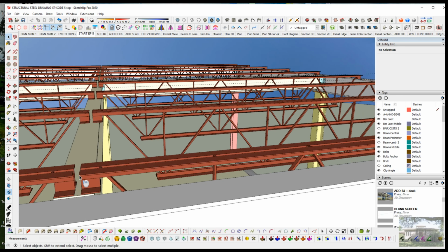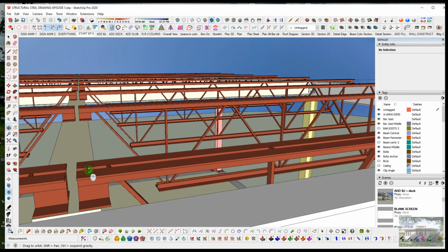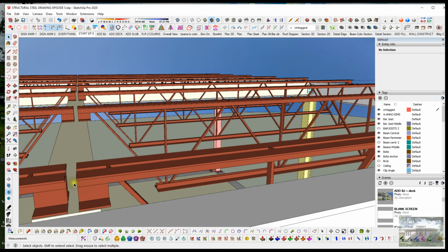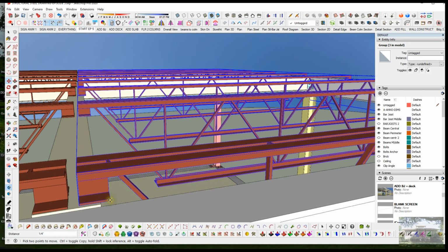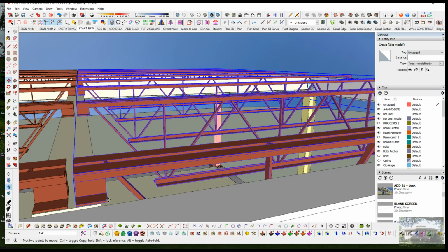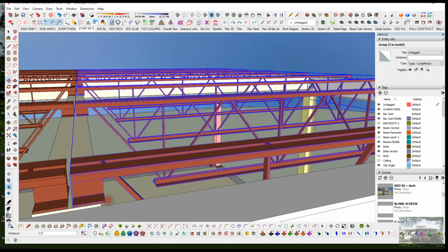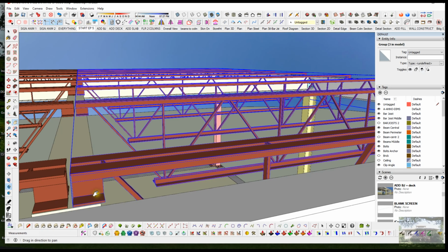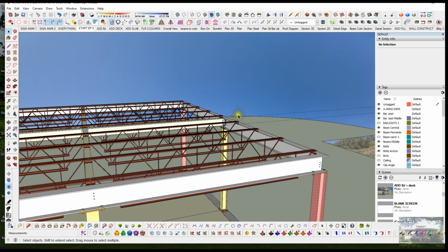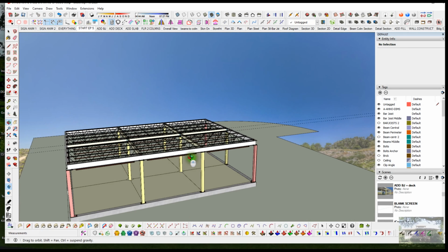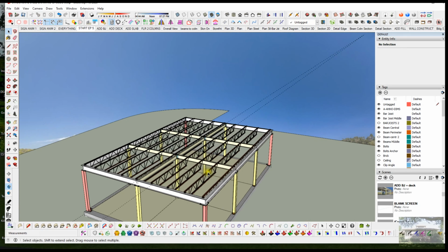And you'll notice, and I did this not on purpose, but it's a good thing to do, leave a space here. If the bar joists expand, that expansion will not cause any problems, because it has a place to expand right here in this joint. You'll have 2 of them, so it's kind of like a control joint. So there's our structure for the metal deck.